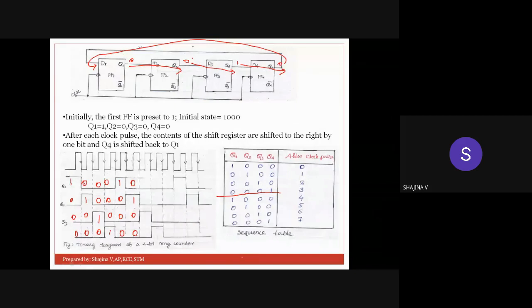Okay. So we can say this ring counter, initially we have set the value 1 0 0 0. It will go through 4 different states. After that, what does it do? It will repeat. So we can say it produces 4 different output states, and then keeps repeating. So for a ring counter, the number of output states is 4. Which ones? 1000, 0100, 0010, and 0001.